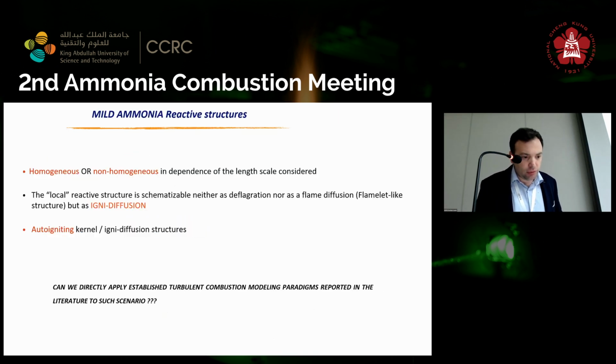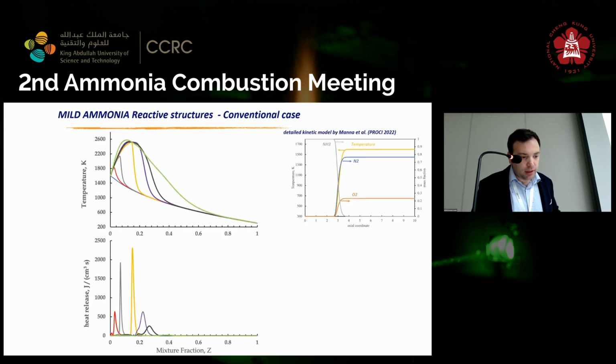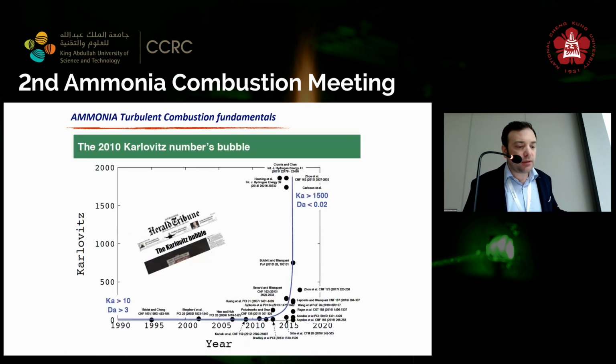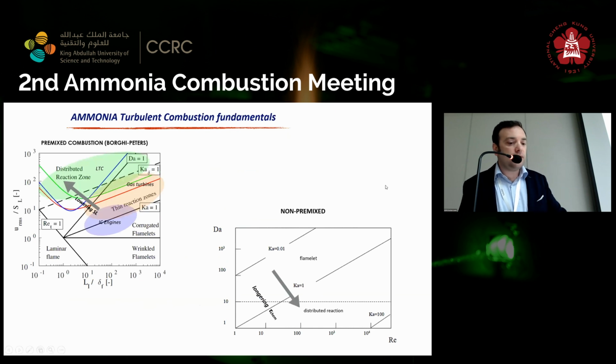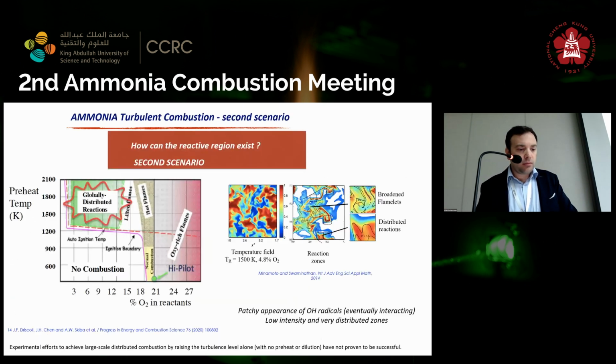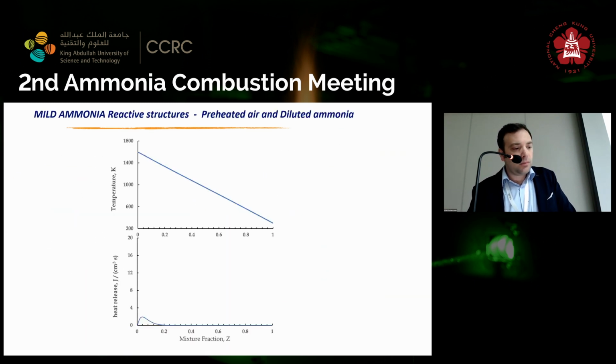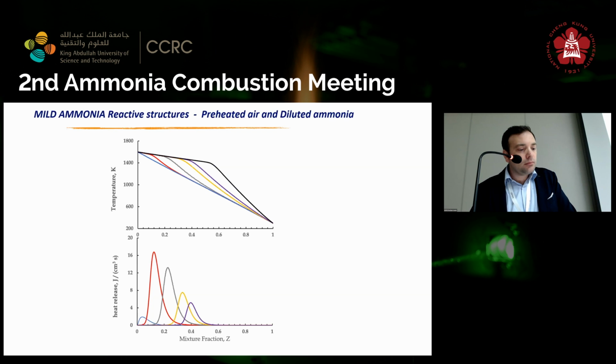So you're referring to this. Yeah, right. That's right. This scenario, right? Yeah. So the second scenario where the temperature is... I was referring to this non-premixed regime. You had this 1D exercise, the second scenario where the boundary temperature is such that the mixture is diluted enough, and the peak temperature is a second scenario like that, right? Okay. So this is just a regular steady flame solution, except if you try to plot the reaction zone temperature as a function of scalar dissipation rate, you're not going to find the regular turning point. There's no boundary between the ignition and extinction branch. It's just continuous. Yeah.